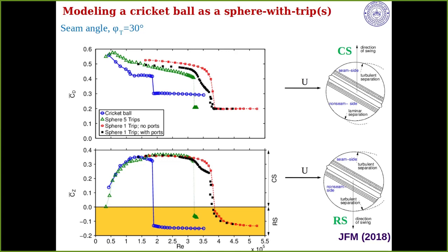The lower surface did not have a seam. But if I go to a large enough speed, it will also eventually become turbulent. Just at a larger speed, but it will become turbulent. We have now reached a speed where the upper surface is turbulent because of forcing. The lower boundary layer has become turbulent naturally. This one is not as efficient as a natural transition.